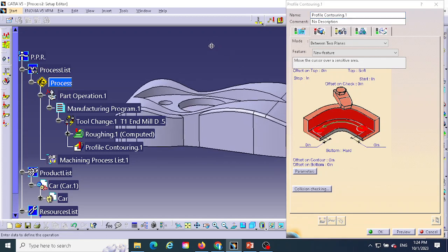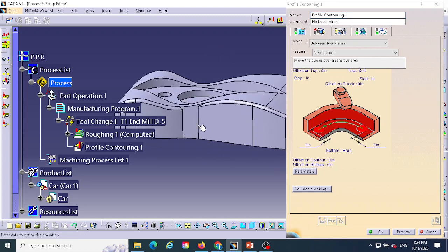So here in the part, what you see is we can do profile contour to machine it all around here. All right, the side, the contour part. So here, as you can see, the outside part is open. This is open or soft. We call it soft. In this point, we change it to soft. You see, it becomes soft. So there is no, this is open space. So just click. We change it to soft, and then we just click.